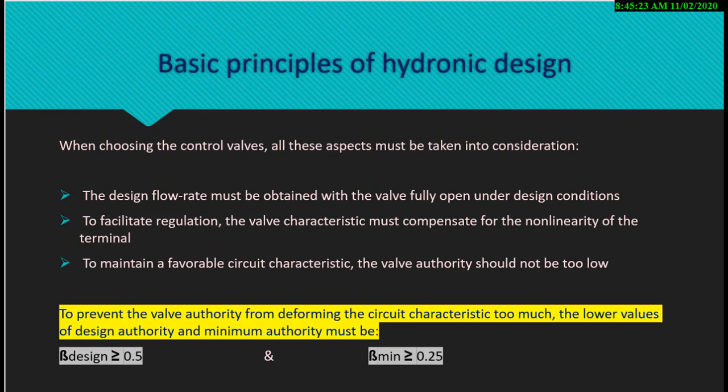Basic principles of hydronic design. We have three basic principles to take into consideration. First, the design flow rate must be obtained with the valve fully open under design condition. Second, to facilitate regulation, the valve characteristic must compensate for the nonlinearity of the terminal.